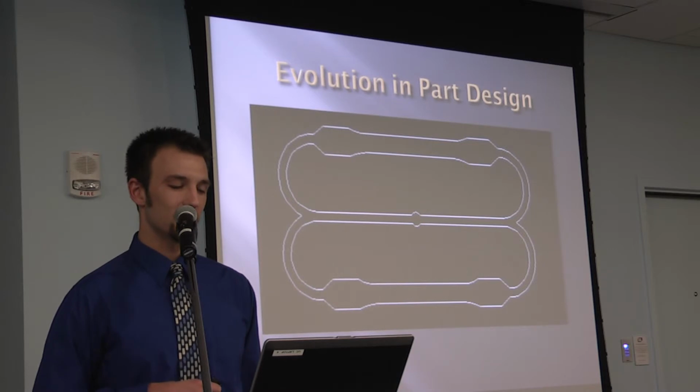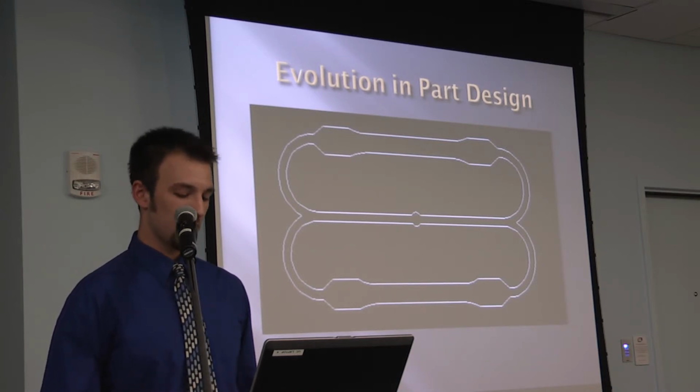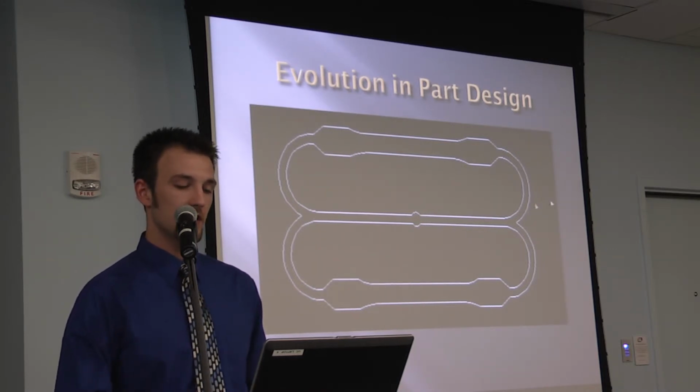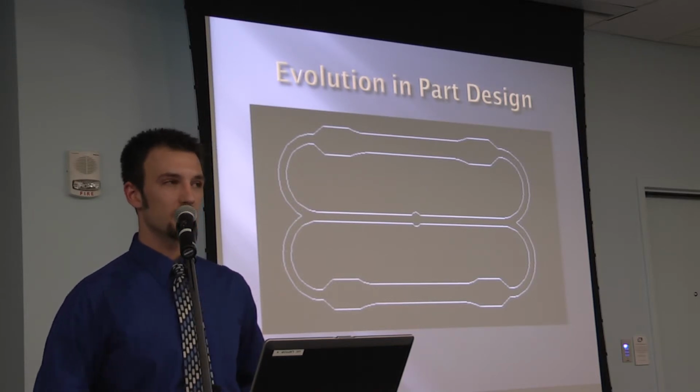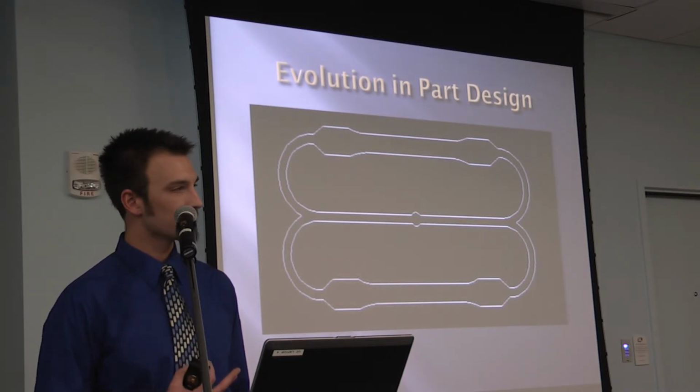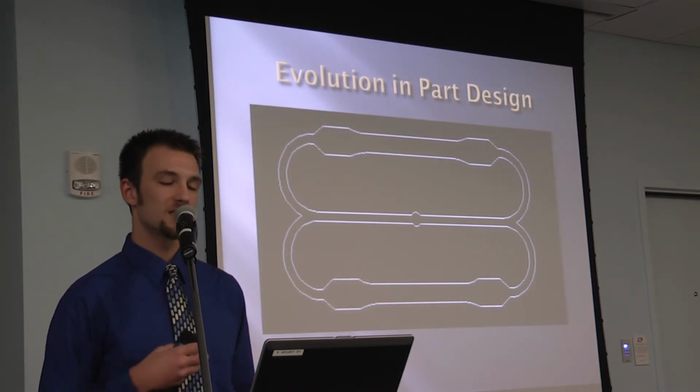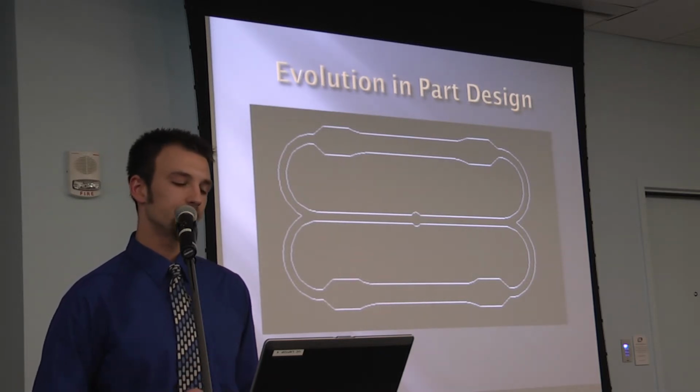Once again, I ran into an issue. The issue here is that there would be a weld line in the center of each part. Along with that, the material flow to this would be different. The molecules would be facing in different directions, which means this could compromise the strength of the product.